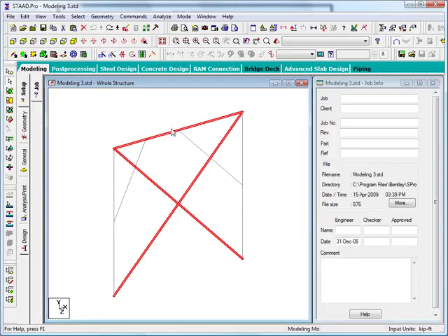The deselect function doesn't seem to work. So we'll correct that by saying that in the drag line mode of selection, we can use the Control key to add additional members, but we can't use it to deselect individual members. To deselect them, we'd have to come back and just click on them to change the selection set.